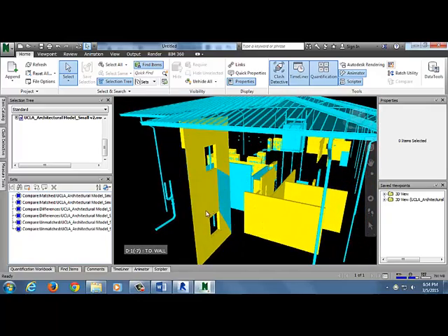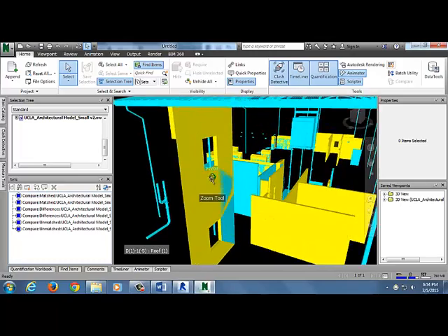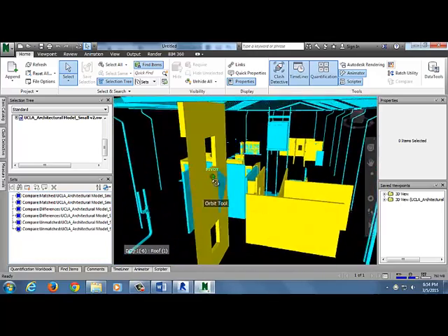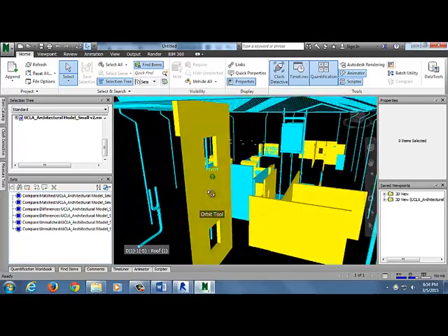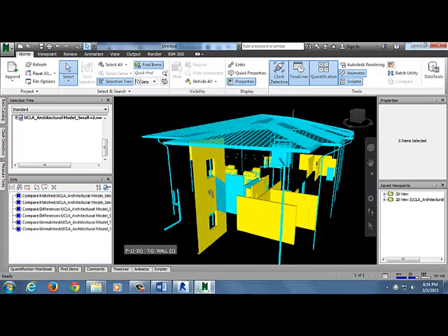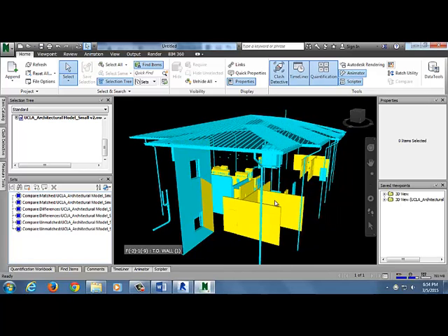Looks like they deleted it but then added back something very similar, because it's taking up the same airspace, right? So this is part of the analysis. Navisworks will flag it for you the way a computer does well, based on certain criteria, and you have to come in and see what this actually means.